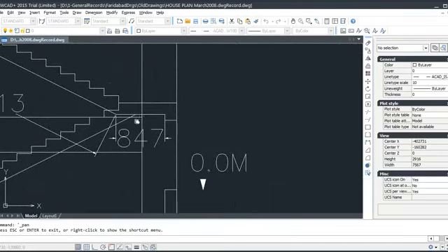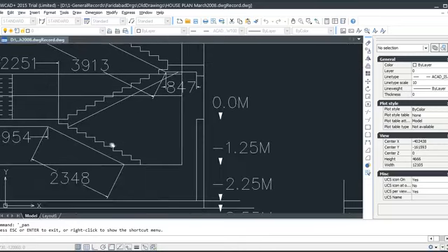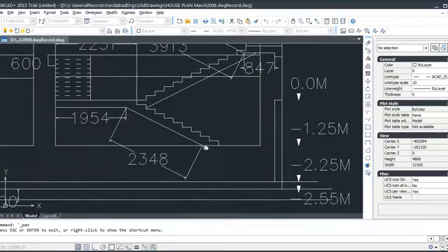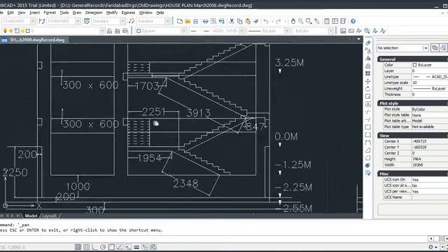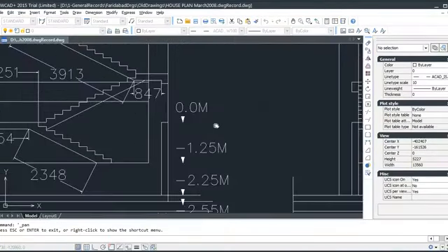This is formwork, but the formwork is here, and that formwork is another one. This is this side and that is that side. So all dimensions are given like this. Here from here, that shuttering, this is also shuttering. Straight away, that carpenter would cut accordingly and fix. This is called a kind of working drawing where work is to be done and levels are given.